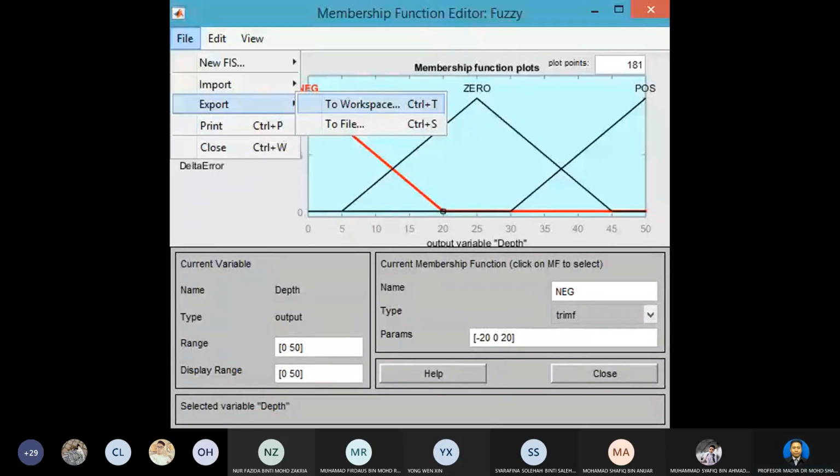If it's not so good, go back to the fuzzy tools, and then change, for example, the parameter or the membership. Change the parameter before running the simulation. Make sure you export to workspace. Every time you change your fuzzy logic, make sure you export to workspace, so that the simulation will be updated to the latest one. Every time you tune your fuzzy logic, export to workspace and then run the simulation, so it will follow the latest one.